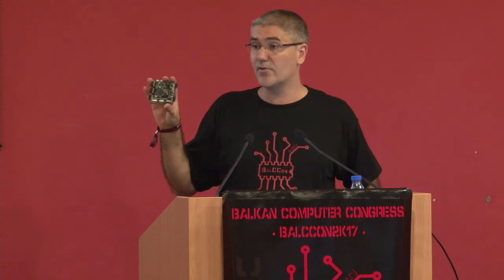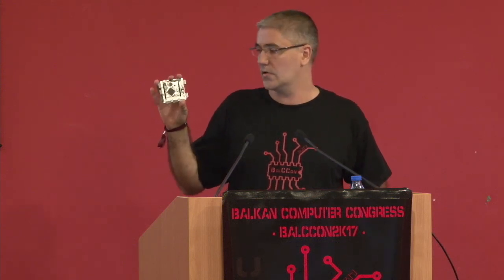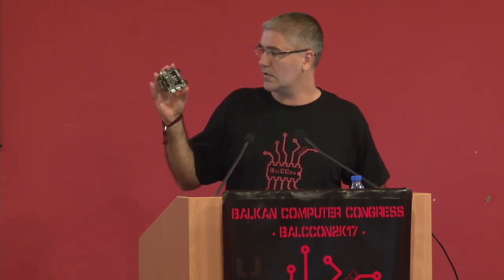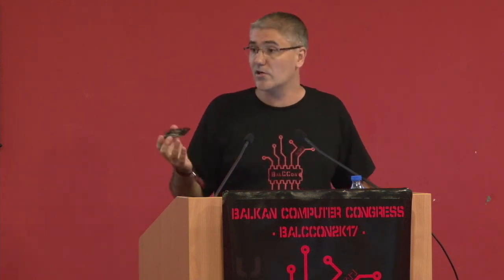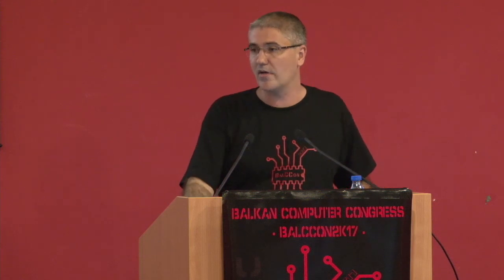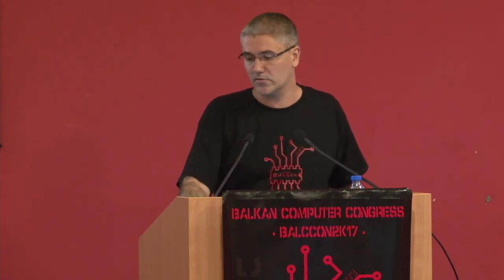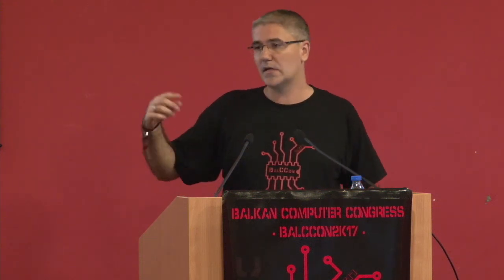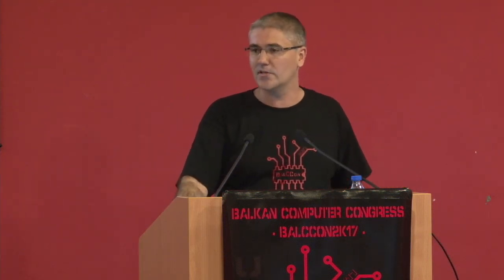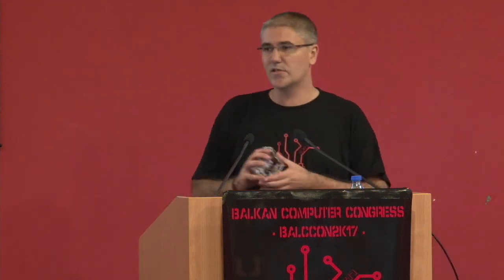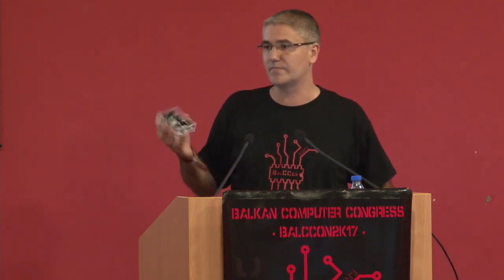And this one has 8K elements and an ARM chip, ARM Cortex M4, I think, so you can create larger products on it because you have more space, and more RAM, and PLLs. It also runs at 100 megahertz, and this one is at 25. And this one is with a Spartan 6. It's from Xilinx.